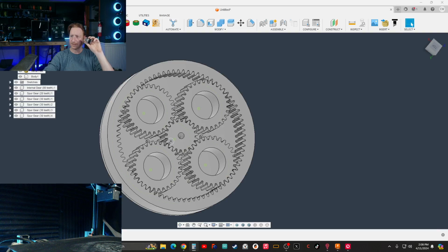If we have a 180 degree rotation and we're dividing that by 1.8, that's 100 steps. So we'd have to have that in our code for this one. 100 steps will give us a 180 degree rotation.